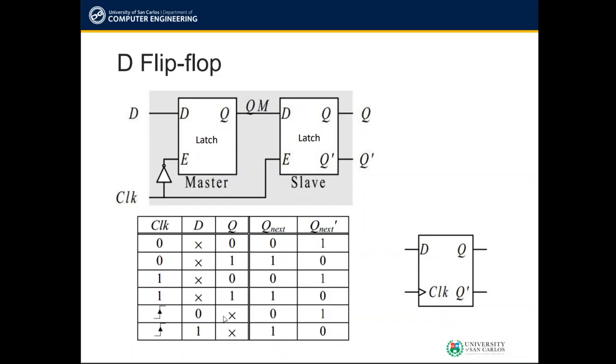Since we are dealing with states, we refer to 0 as reset and 1 as set. Again, I'll remind you that this is Q present and then Q next. Q present is here, and Q next will be here. Basically, this is again the inside of your D flip-flop.